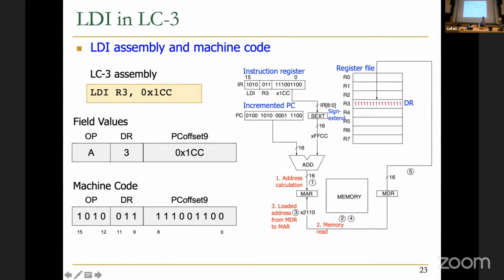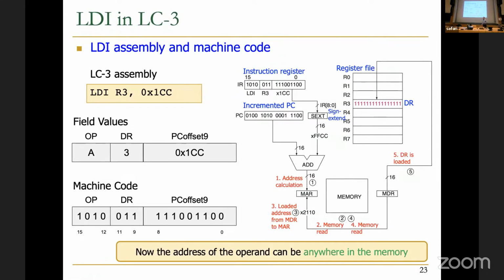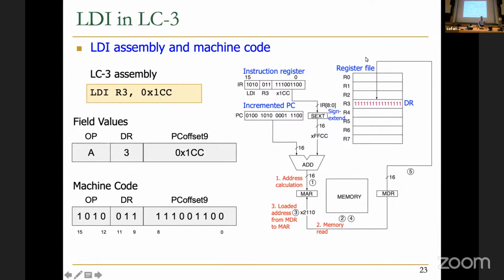Now you can address anything in memory, right? But you just need to put the pointer close to your instruction. And you know already what the distance should be. It could be at most 255 words later than the instruction, PC plus 255, plus 1, of course, right, plus 2, sorry. And also 256 words earlier.